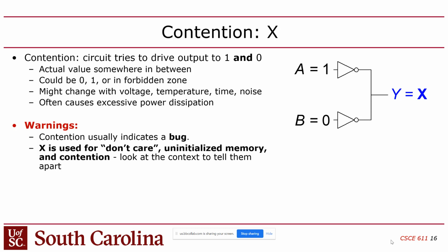Now, there are some ways that you can do some modeling and simulation, test benches and such, where you can actually implement other data types. But in this class, we're going to focus on SystemVerilog that is synthesizable, meaning that it can be converted into hardware. And so we're going to stick to using just binary data types. So you can have variables and inputs and outputs, but it's all assumed that they're just binary signals with a certain width.